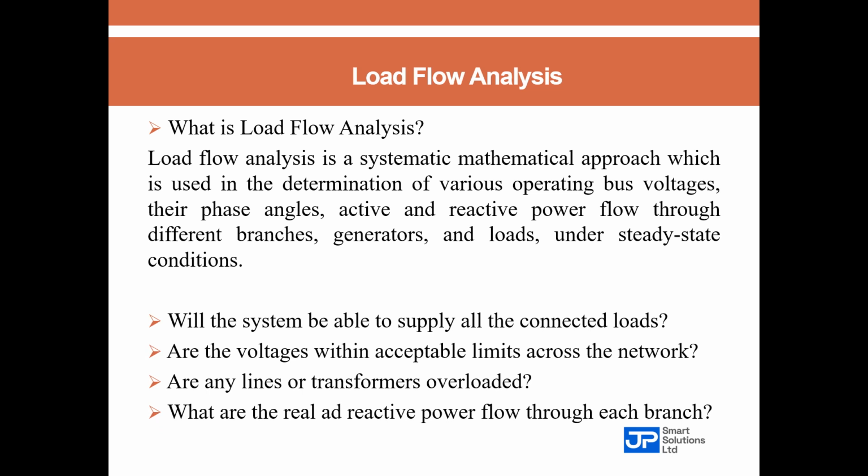Let me share a story. One of our clients was operating a large commercial complex, and they started experiencing frequent voltage dips whenever their chillers kicked in. Now, at first, you will suspect the utility, just like they did. They suspected there was a problem from the utility. But then we were consulted, and after we modeled the system using ETAP software, we carried out a load flow study, also known as a load flow analysis, and the problem was crystal clear.